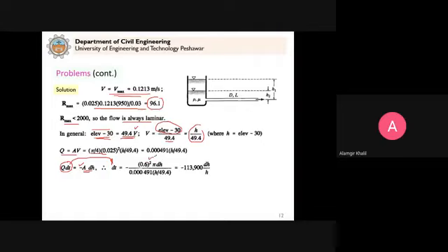So now this 0.6, this is for the tank, 1.2 diameter, so radius is 0.6 meter. Now this will be equal to this expression for dt. Now you want to calculate the time, just integrate this equation here. This is constant, write down outside the integral sign, and we are left with dH by h. So integral dx by x, that is log of x. So here dH by h, log of h.